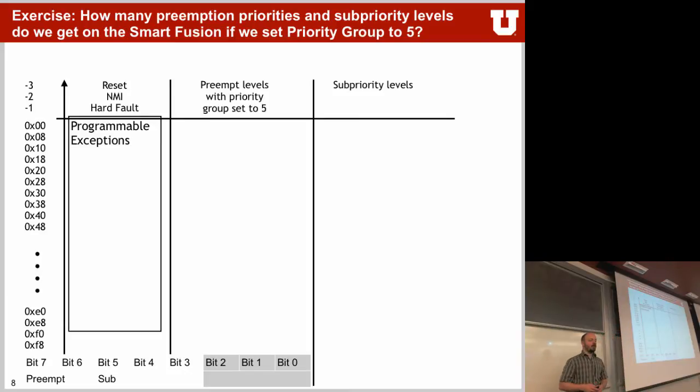Okay? Now, let's assume we have 2 different priorities. Actually, these are all of the possible priorities given this bit mask. If you notice here, we are always incrementing by 8, right? So these 3 bits will always be 0. So we have priority 0, 8, when bit 3 is 1.